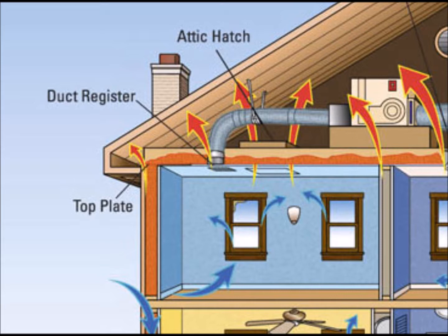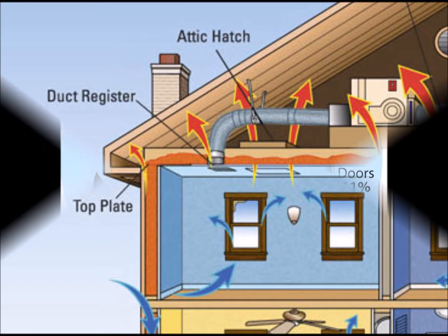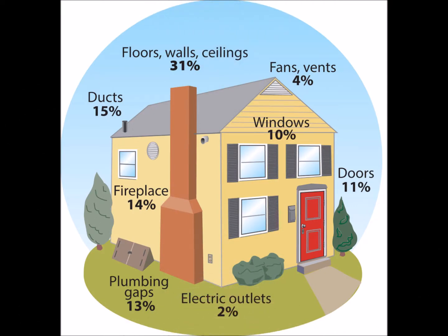If you're in a cold or especially cold climate, moisture tends to go from the interior conditioned spaces to the exterior through the wall and ceiling assemblies. The primary concern is preventing interior warm and humid air from flowing outward into a building's exterior envelope assembly in winter months. Such airflow can carry a large amount of moisture and cause condensation in the wall.